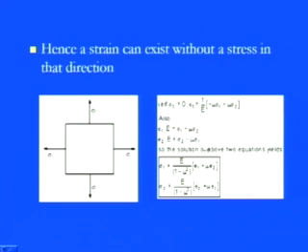So, if we resolve these two relations, we can simply calculate the principal stress formulas. We get sigma 1 equals E divided by 1 minus mu square, into epsilon 1 plus mu times epsilon 2. Similarly, if we put these values in the equation, we get sigma 2 equals E over 1 minus mu square, into epsilon 2 plus mu times epsilon 1. So the only change is where the Poisson ratio multiplies.